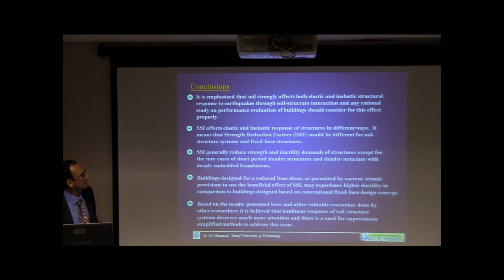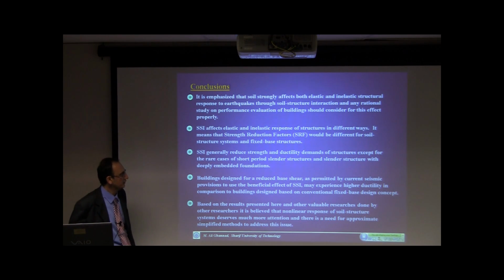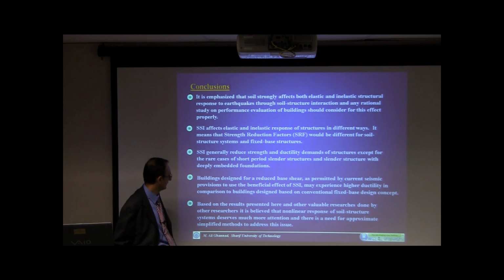It's emphasized that soil strongly affects both elastic and inelastic structure response to earthquakes through soil-structure interaction, and any rational study and performance evaluation of buildings should consider this effect properly. Of course, as known, SSI affects elastic and inelastic response of structures in different ways. It means that strength reduction factors would be different for soil-structure systems and fixed-base structures. Soil-structure interaction generally reduces strength and ductility demands of structures, except for the rare case of short-period slender structures and slender structures with deeply embedded foundations.